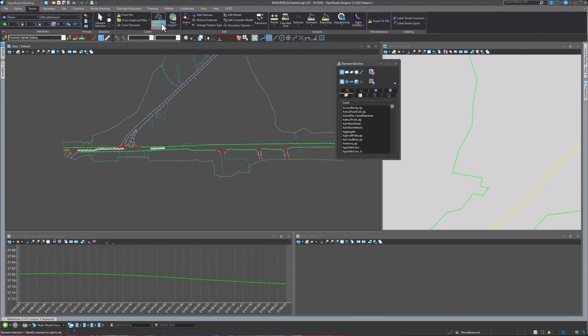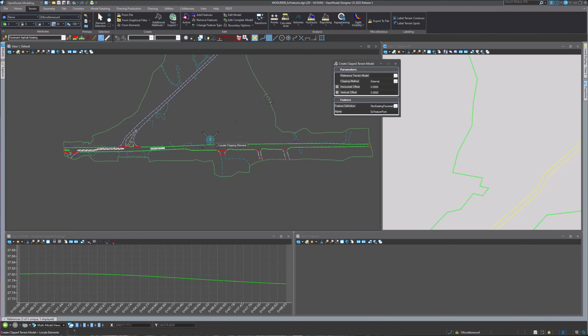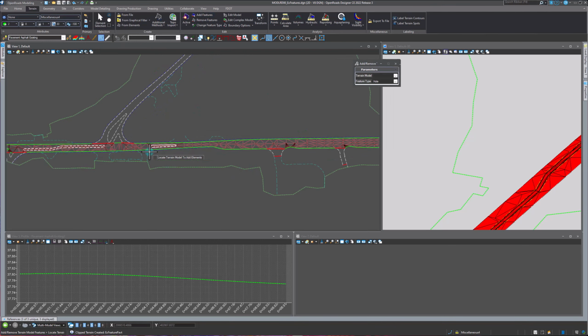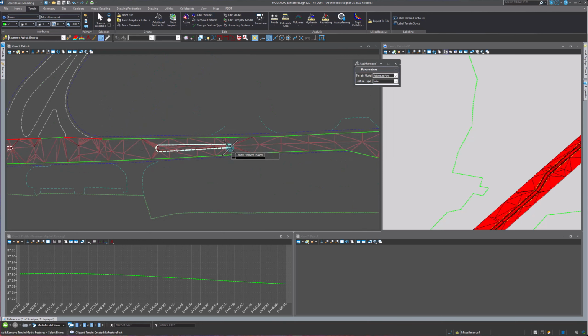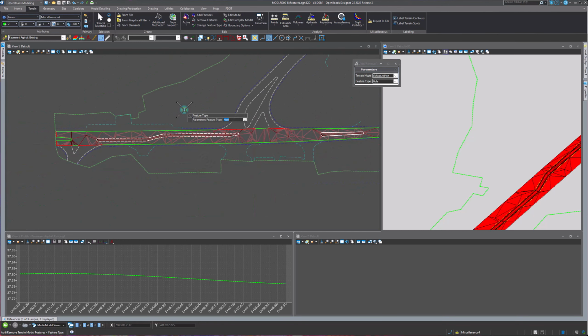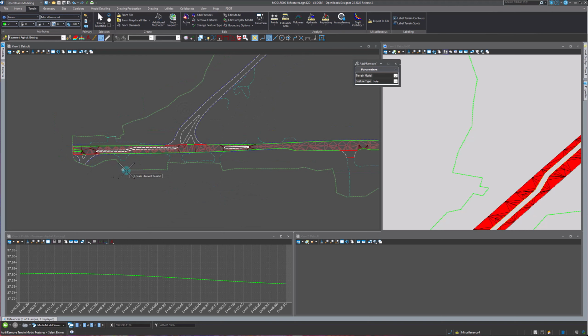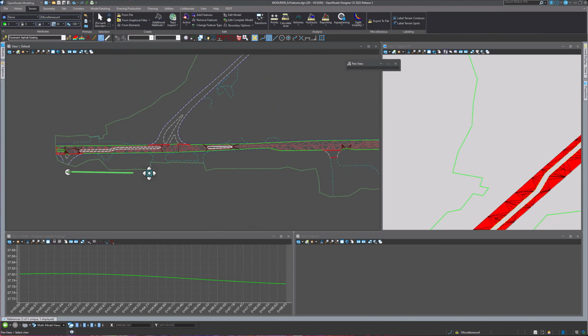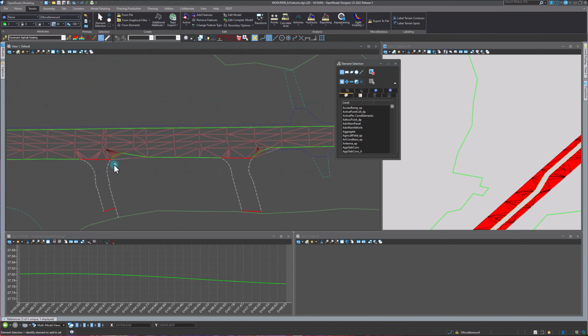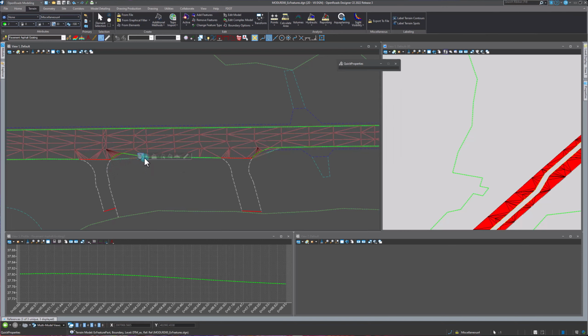And then just to show this again, we'll create that clipped terrain model. Existing terrain, clipping element, click through all this stuff, make sure we've got an external. We've created that again, and then we'll go ahead and add those features to that terrain model. Make them a whole. And we've still got some stuff here where it's trying to clip out of there. So maybe let's take a look at this if this fixes it.